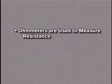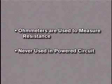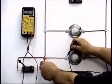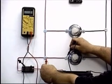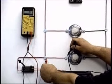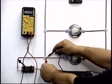Ohm meters are used to measure resistance in components or sections of a circuit. An ohm meter supplies its own power to the component or circuit being tested, so an ohm meter should never be used in an active, powered circuit. Like voltage, resistance is measured parallel to the component or circuit being tested. An ohm meter is connected to each end of a segment of the circuit that is suspected to have a circuit fault, and the resistance in that segment is read in ohms. If there are no working components or loads in the segment, resistance should be near zero. Higher resistance readings would indicate a continuity problem.